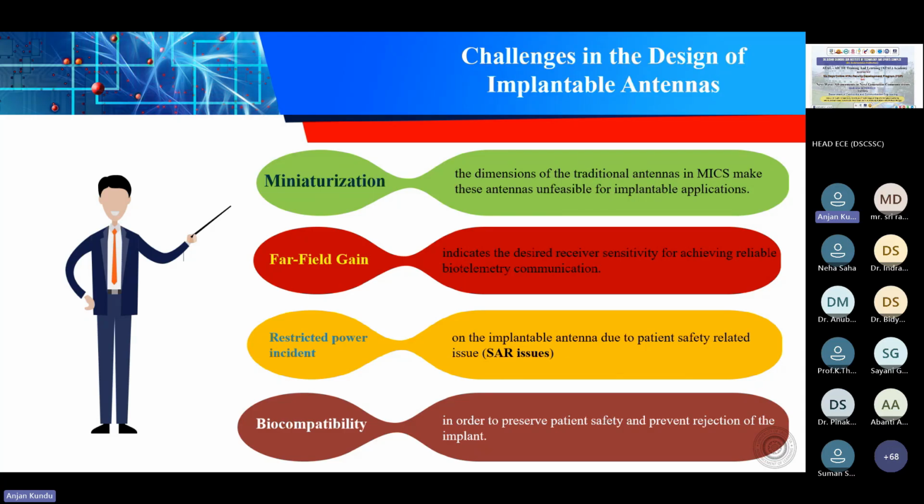We can't increase the gain. If we want to increase the gain, it will cross that SAR limit. Also, whenever we want to increase the gain, miniaturization can't be done, because the dimension of the antenna, the radiating element or radiating aperture, will get larger. So definitely there will be a compromise between miniaturization and gain. Far field gain is a crucial factor whenever we are designing implantable devices. This is the SAR issue.